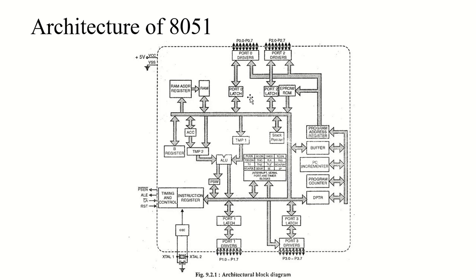Then we have the interrupts. I'm not going to detail the interrupts, but let me give you a glimpse. Whenever the microcontroller is executing a program, if the user wants service for an input output device, then an external asynchronous input informs the microcontroller that it should complete the execution of the current instruction, and then fetch the new routine that will service the requesting input output device.